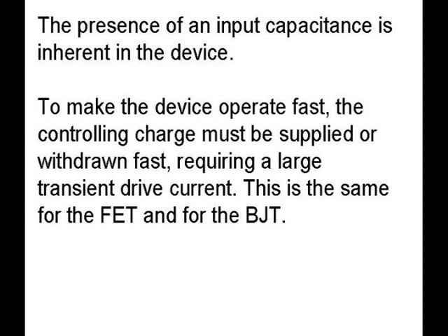The input capacitance is an essential component of the model, because you have to stuff charge in to turn it on, you have to yank it out to turn it off. When you charge up something, that's like a capacitance. The faster you want to turn it on or off, the faster you have to supply and withdraw the controlling charge. It takes a large transient drive current. And that's exactly the same in the FET as it is in the BJT.